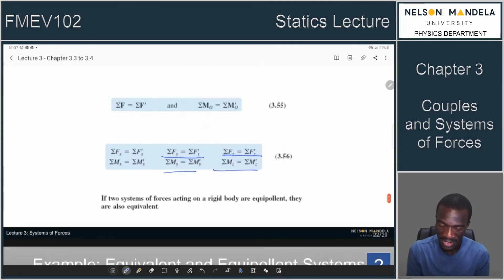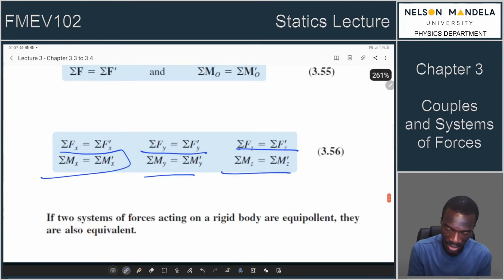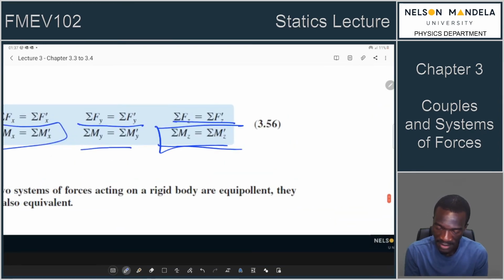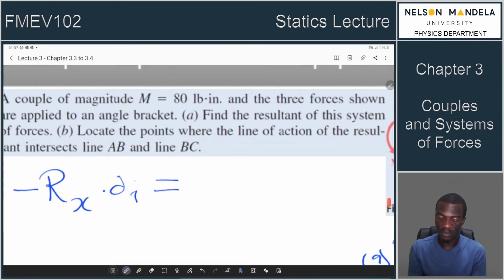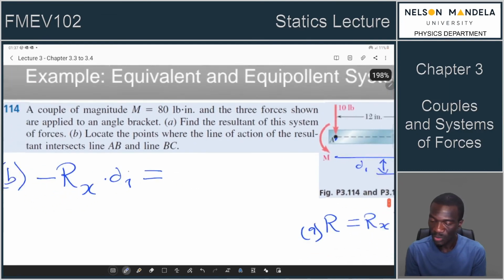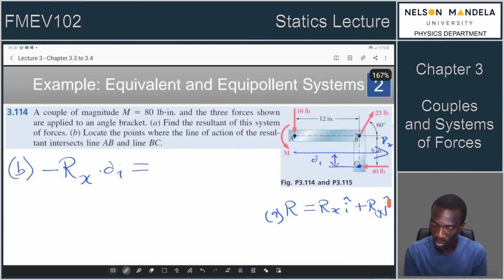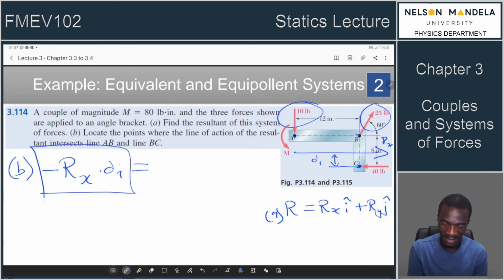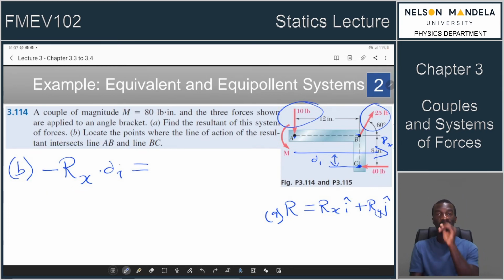So we are now simply pulling out this equation. This was in the K, so actually we are pulling out this equation. The sum of all the moments must be the same. So when you look at the moments of each and every one of these forces about the what? About the point C, they should also give you this horizontal component's moments.